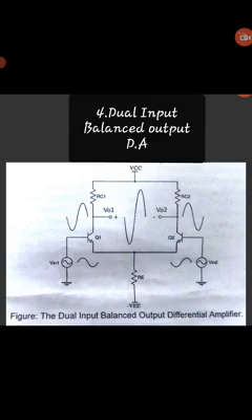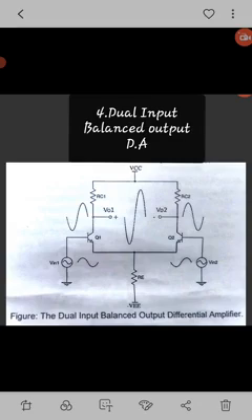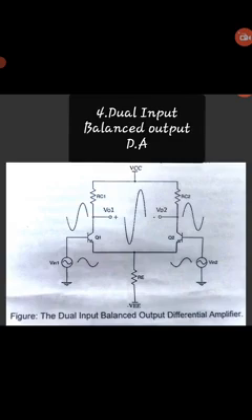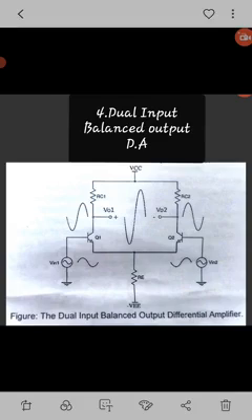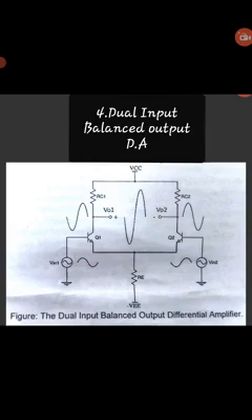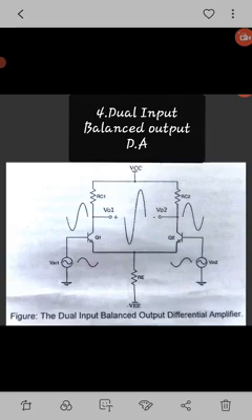Input signals are applied at the base of each transistor and the output is taken from both collector terminals. There won't be any unnecessary DC content in the balanced output, as the DC contents in both outputs get cancelled by each other. This has a double-ended input.